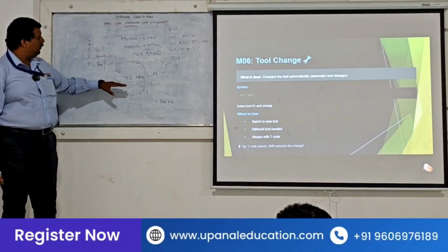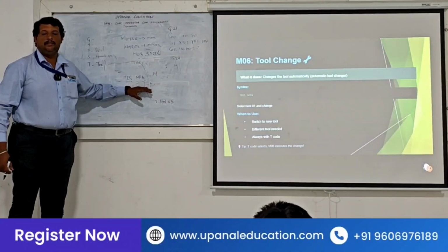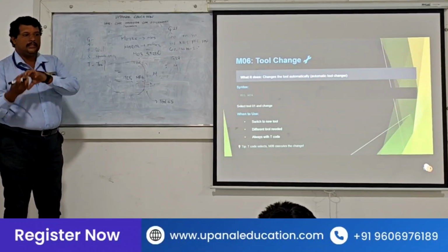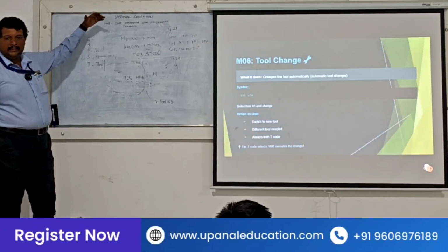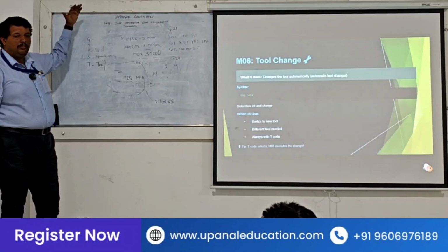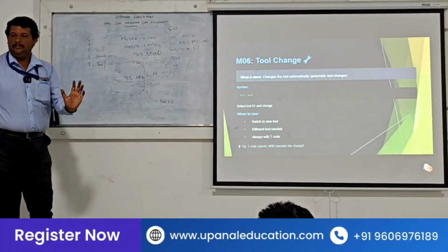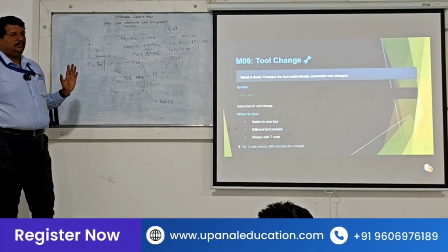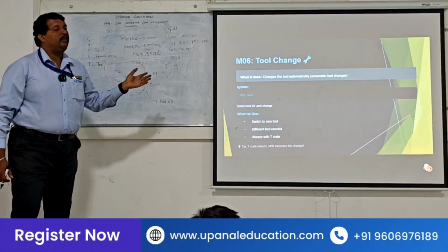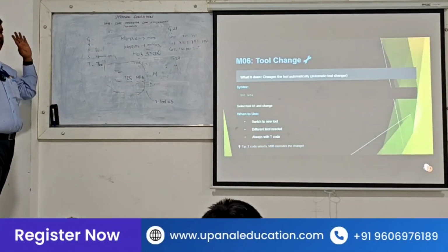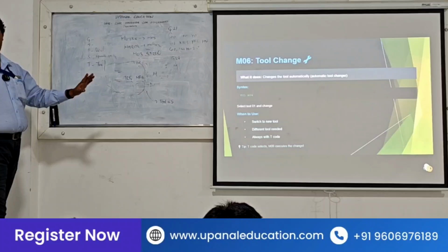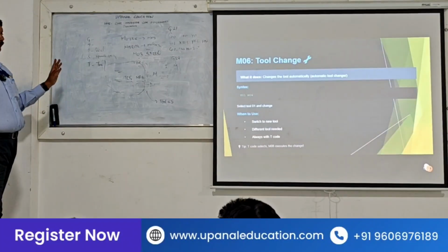If I give the code T05 M06, whatever tool is there will go back to the ATC and tool number 5 will come. Then if I want to call tool number 24, what will I do? I will put T24 M06.